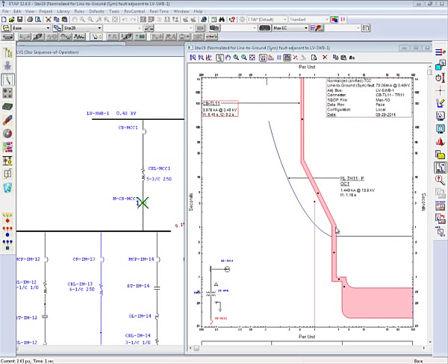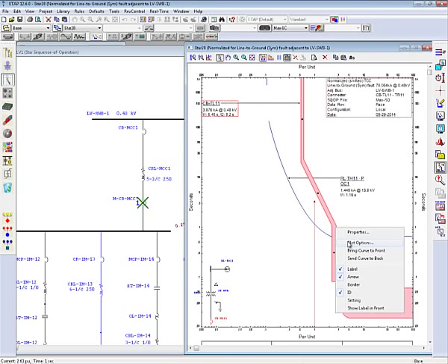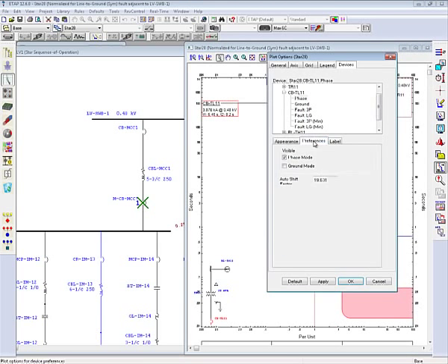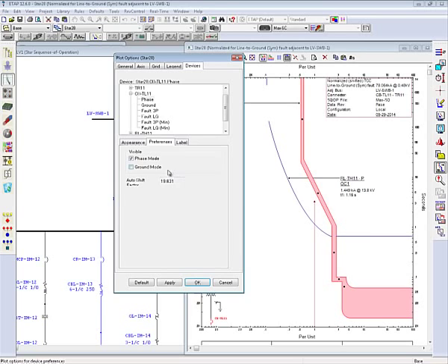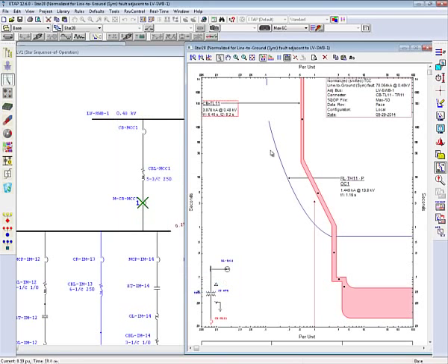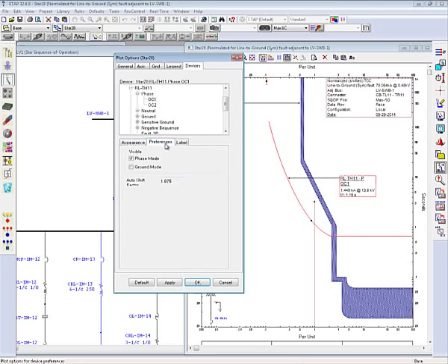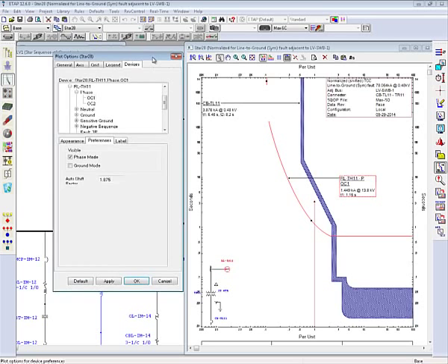These shift factors can be observed from the plot option preference page of the Star View. So the shift factor for CBTL11 is 19.631 due to the through fault current through CBTL11, whereas the shift factor for the relay is 1.875 because of the through fault current through the relay.